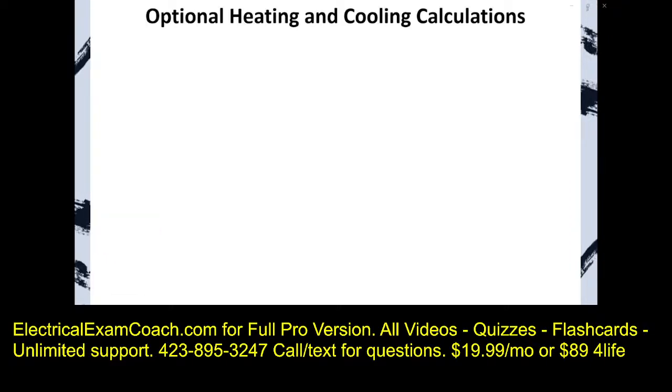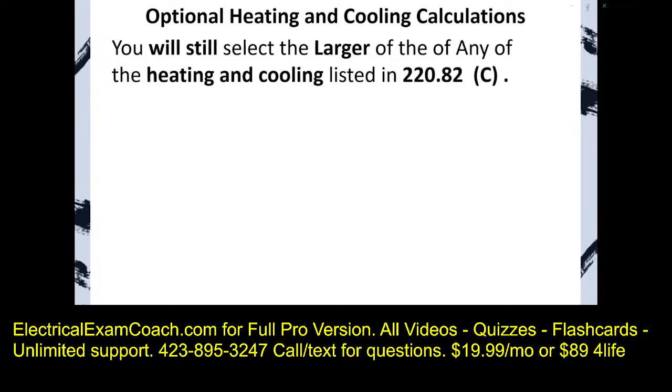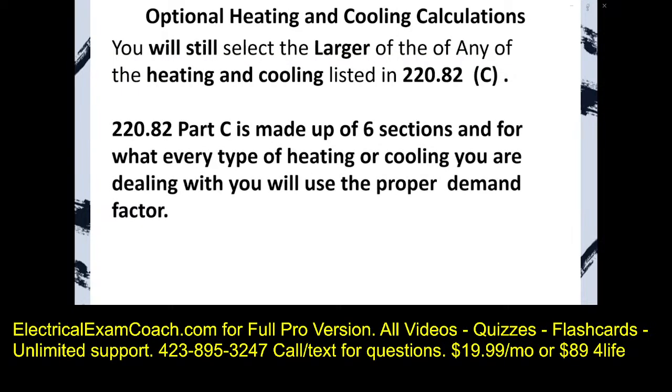With the heating and cooling optional method, we still will choose the larger of any two of the heating and cooling listed in 220.82c. It's very simple. If you get an optional method whole house or an optional method heating or cooling, you just go down and read the prescription for each part. There are 6 different parts. It tells you what to do.